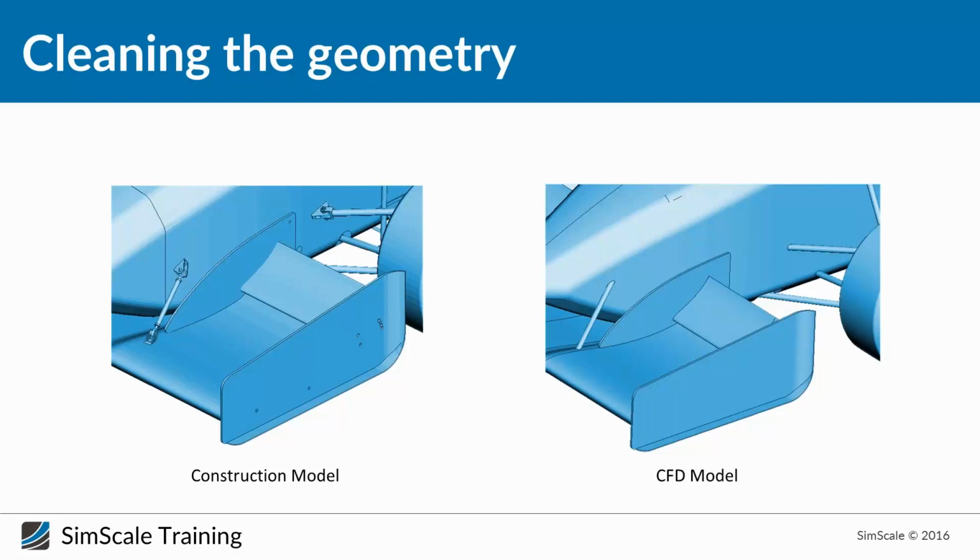But the most important thing, because we have all these elements and details, is that sometimes we'll find problems in the mesh, where the mesh cannot really cover all this geometry because the angle is maybe really sharp. If we take a look inside here, we can see that the surfaces are really sharp and maybe the mesh cannot get there, and then you will have problems. So you will not represent your geometry in the right way, and this will create a lot of problems.